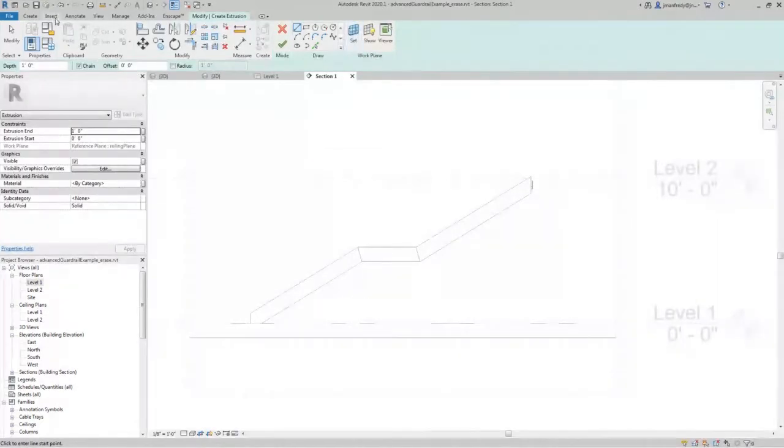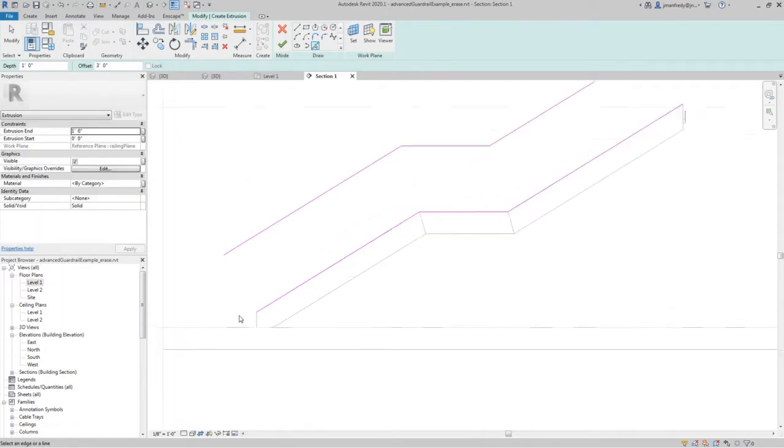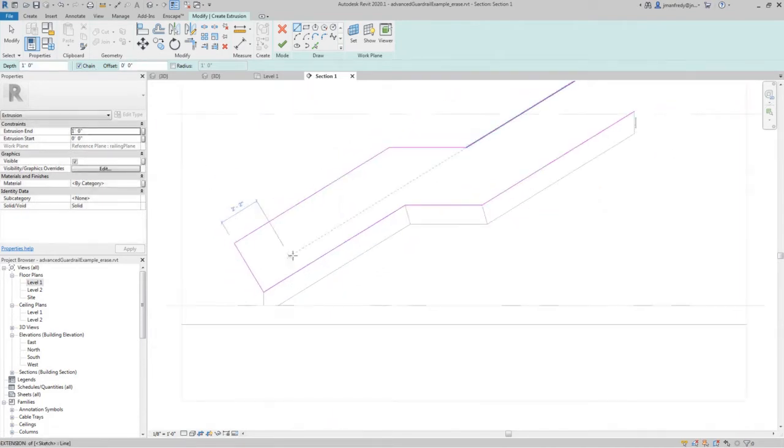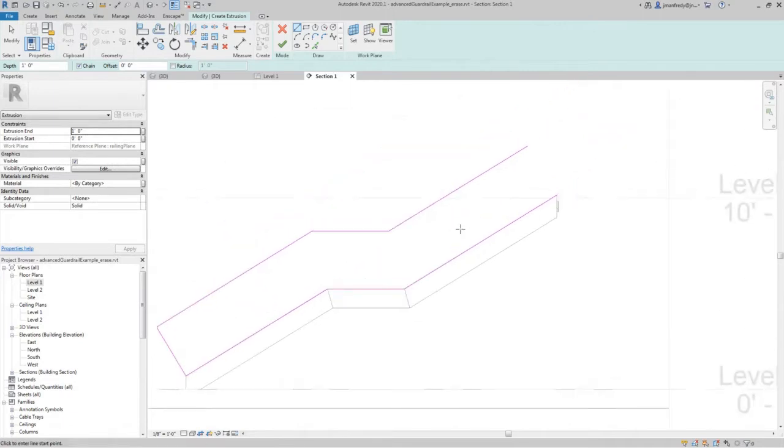So now I can draw an extrusion. And as you know, I can just pick objects here. I can just follow along this edge. Let's say I want it to be offset by 3 feet. I can just pick 3 feet. I can begin to offset, or whatever dimension you're after. And then maybe here, I want to draw an object that connects. I don't want it offset though, make that 0. Connects there, so my railing is going to be at an angle like that.